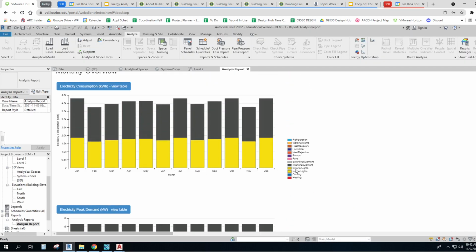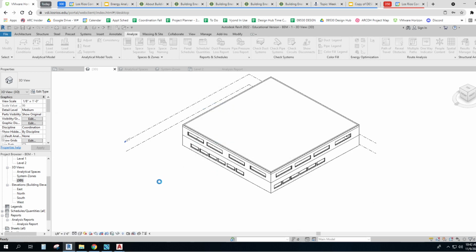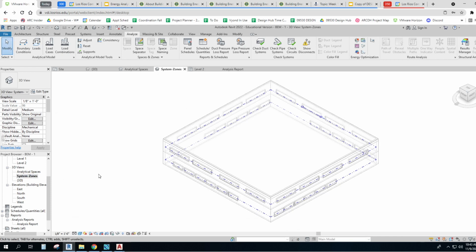Okay? And so I'm missing a lot of stuff in here. But my numbers are low. That's like 4.3 thousand. So they're all under 4,000. So you'd want to know, why might that be different? Well, it's different because I haven't really built a building. I just put up 2 zones. There's no interior zone, no perimeter zone. I don't even know what kind of walls I've got here. I don't know much about this building.